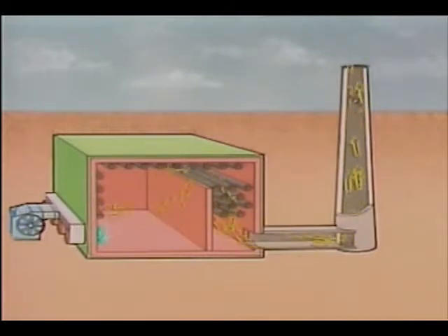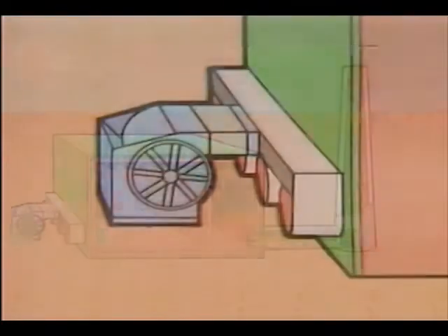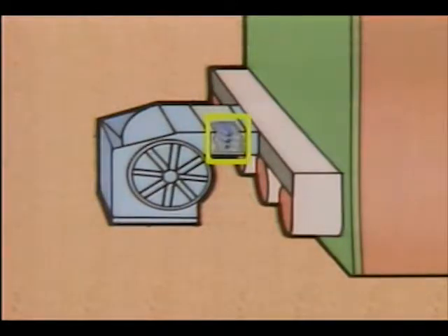In a forced draft furnace, airflow is controlled by coordinating the positions and operation of the stack damper, the burner registers, and the fan. Some forced draft fans have dampers or louvers on the discharge side of the fan.